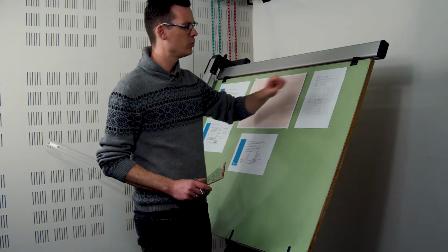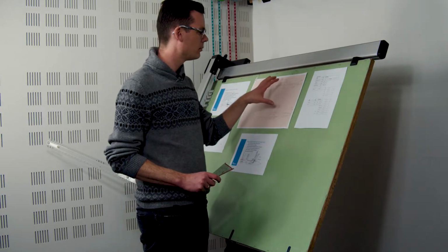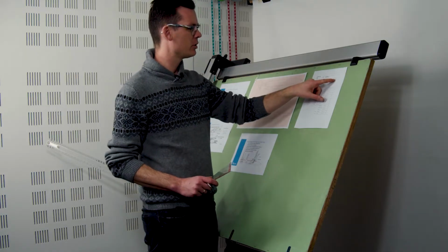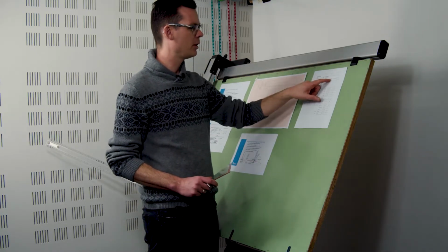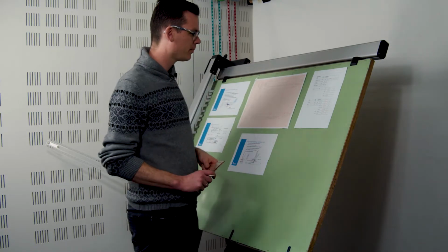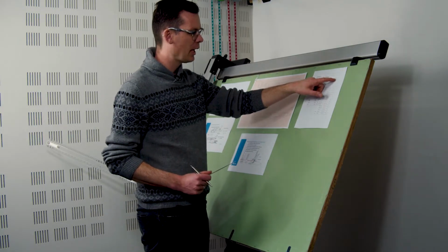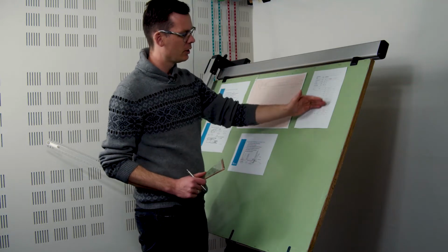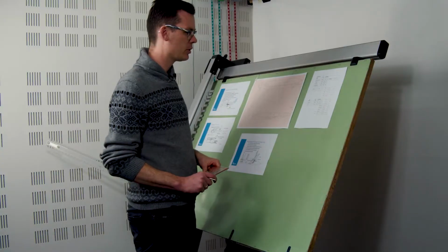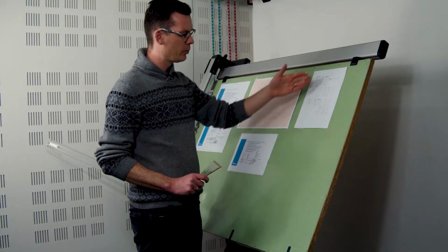In that exam, we had assumed a position for the engine. In this exercise, you saw I actually drew in the engine, which led to a slightly different position. So we start with an engine which is a little bit more aft than on the exam. It's about 77% of the fuselage length, at least that's where the CG actually resides. That also gives slightly different results downstream and results in a slightly more aft located wing position.